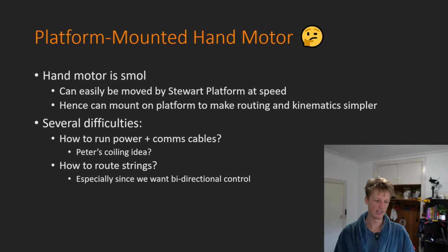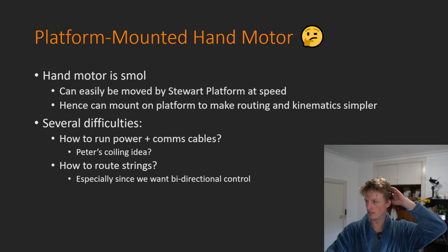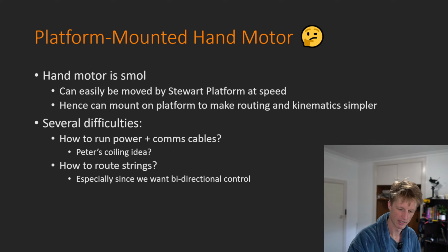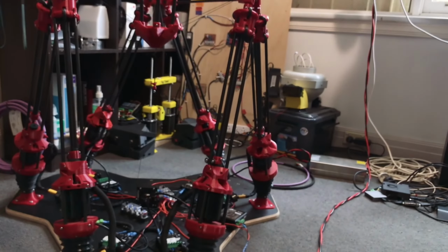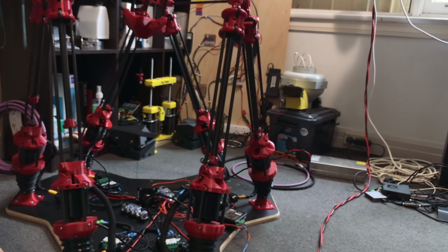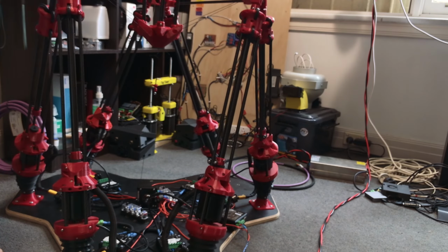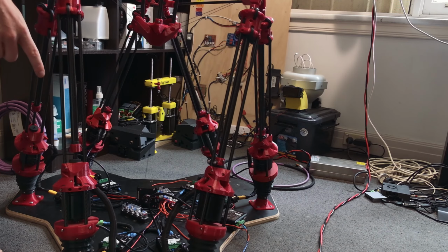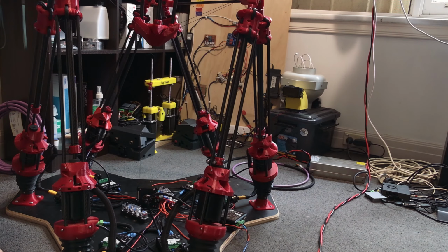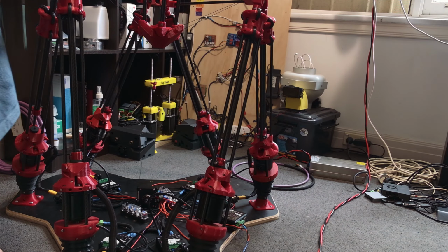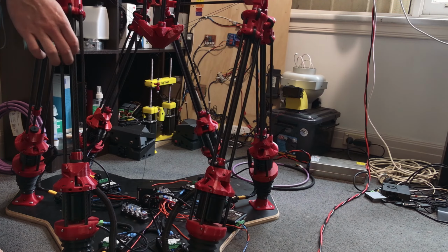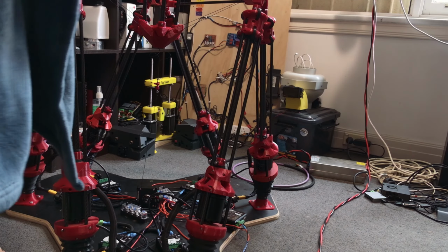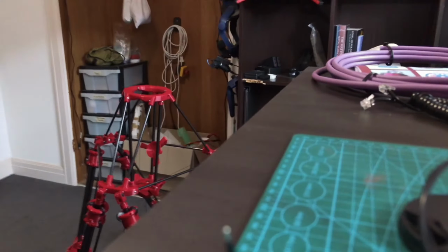What I mean by this is we want the hand to be similar to the legs, insofar as for the legs, wherever I move this main rod, the motor will always move as a result. If I pull it out, the motor will spin one way. If I push it in, the motor will spin the other way. So the exact position of this shaft is keyed to the position of the motor. And I want the hand to be the same way.